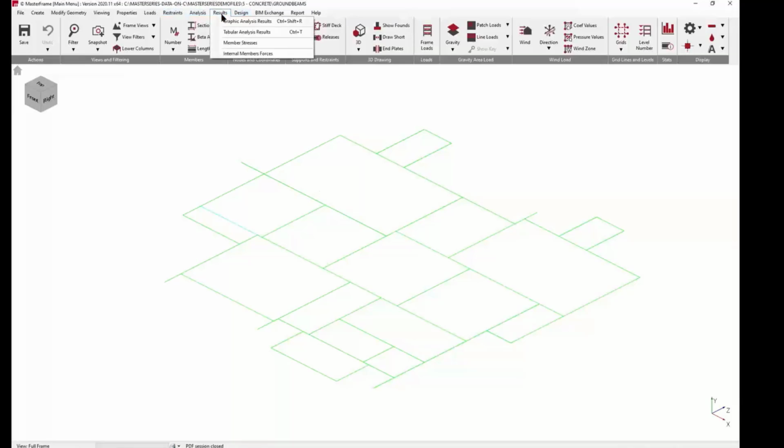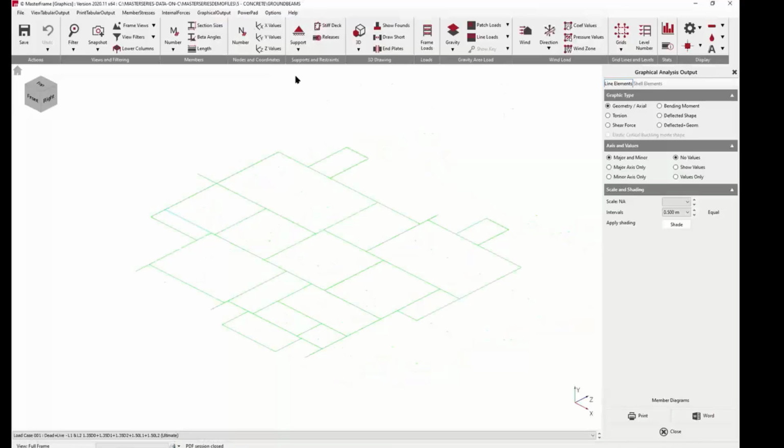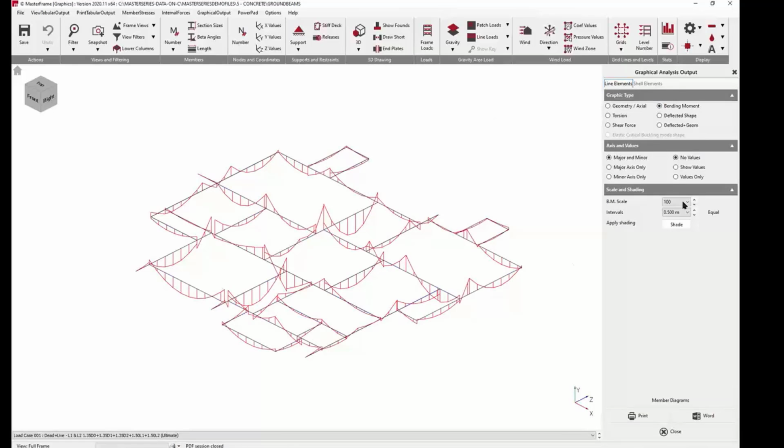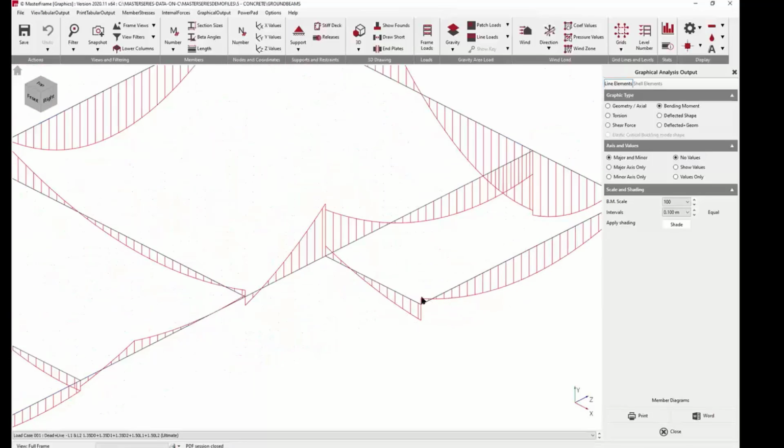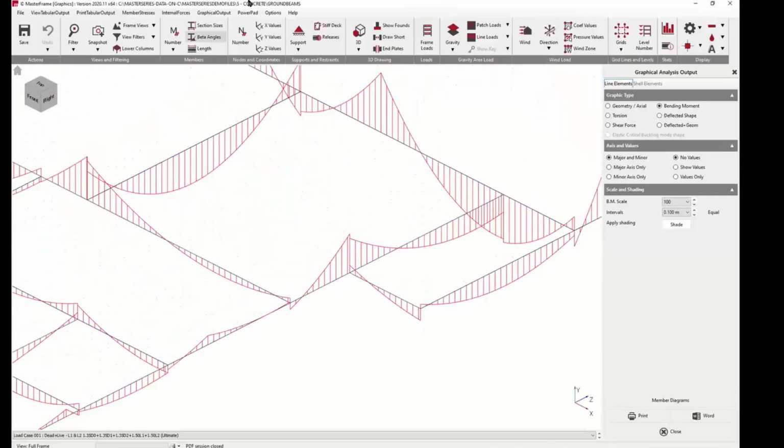Now, let's look at our results and our graphical results. And we probably don't need to see those in green, so I'll just tell it not to draw them by section. And there we go, bending moments. And I can just scale up the number of hatches. And what we're seeing here is at the ends hogging moments, and strangely enough, a kick down here. And if we look at these two values and just turn off measure, we have 6.2 and 16.5.